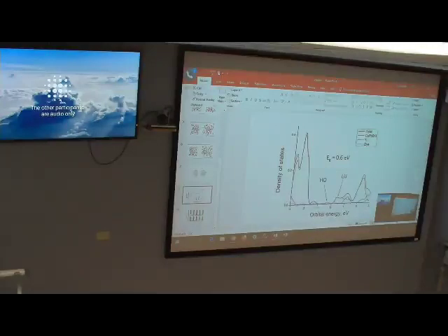These interfaces are parts of photovoltaic devices. Photovoltaic devices are assembled in sequential chains. Each of them generates voltage and current, and the individual unit cell works in presence of others. So typically, the regime of operation of a photovoltaic cell is under external electric field. So an account of external electric field may change the efficiency of the photovoltaic cell.